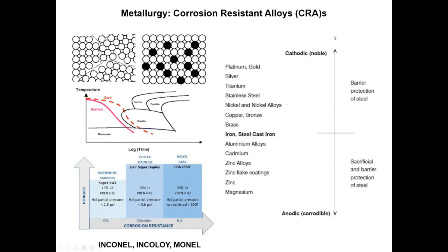Now, let's start talking about materials and the way we can mitigate corrosion. One way, of course, is to look at metallurgy as a solution. That is the use of corrosion-resistant alloys, whether it be in the type of grain or distribution of metal species or dope metal species, or the percentage of chromium and other less corrosive species that can actually not only improve the corrosion resistance, but some of its mechanical properties like modulus and flexibility.